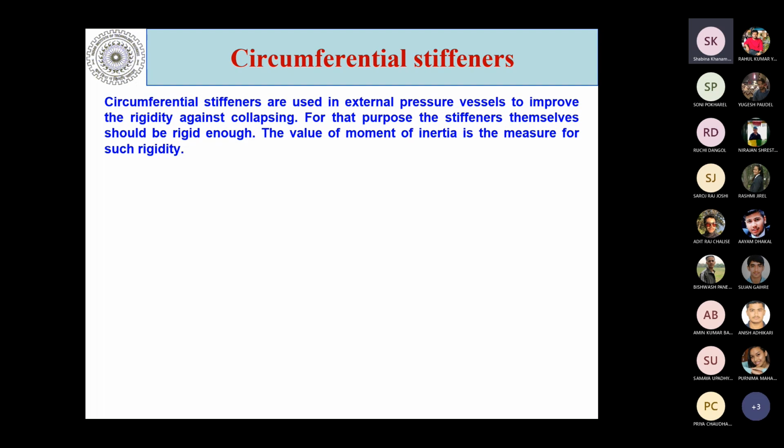So these stiffeners should be rigid in themselves. Okay, so we need to check the strength of these stiffeners with one value, and that is basically moment of inertia.